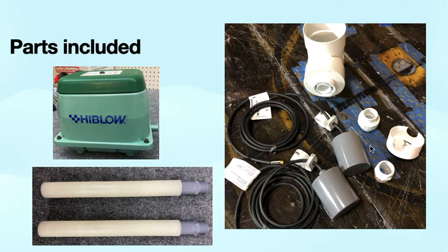And the unions, here's an adapter for the top of that pump to pare it down from that 1.25-inch threaded to that 1-inch, so all you're having to use is that 1-inch PVC. Here's just an orifice shield with a screw in it. Depending on the kind of tanks and the style of the opening, this may or may not be feasible, but regardless, we supply it. If you have a plastic riser, this will drill right into the plastic riser, and a 1-inch PVC will snap into that curve right there, and that can hold in place the float tree that you have for your 2 floats.